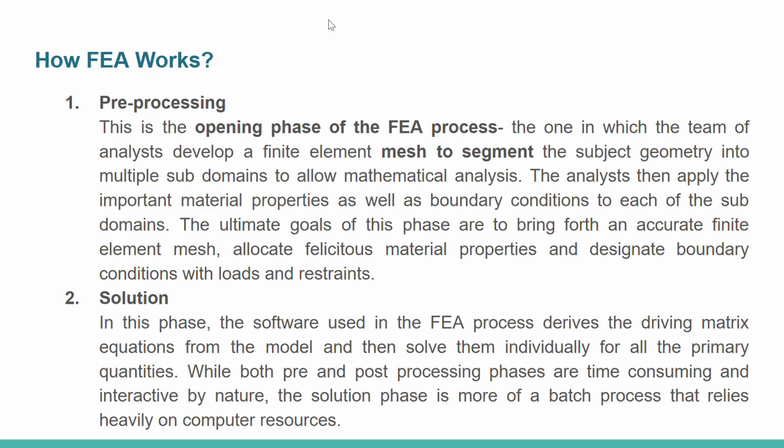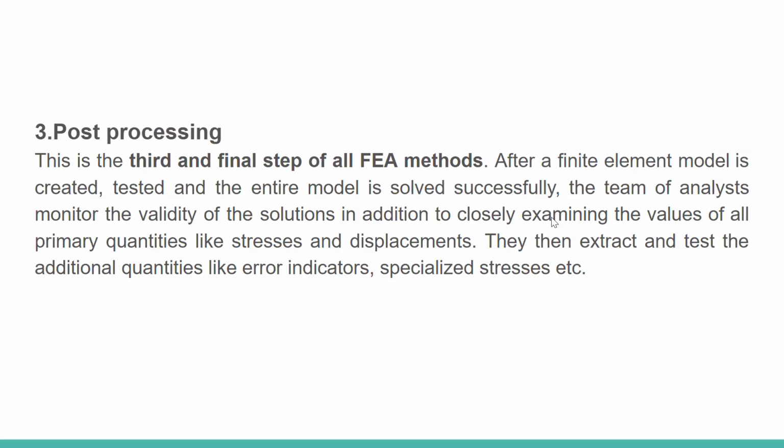Third is post-processing. This is the third and final step of all FEA methods. After a finite element model is created, tested, and the entire model is solved successfully, the team of analysts monitors the validity of the solution in addition to closely examining the values of all primary quantities like stresses and displacement. They then extract and test additional quantities like error indicators, specialized stresses, etc.